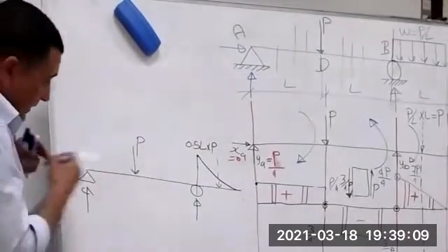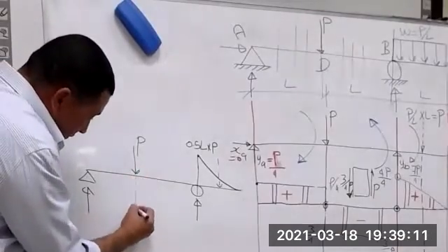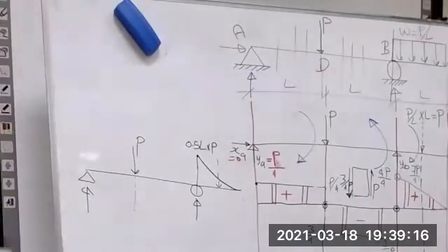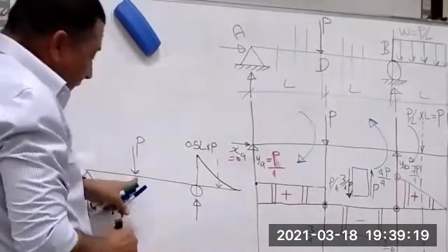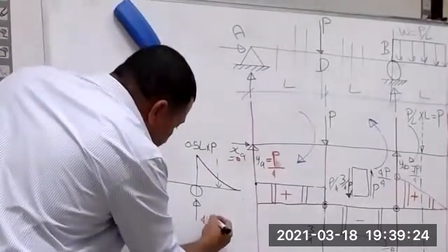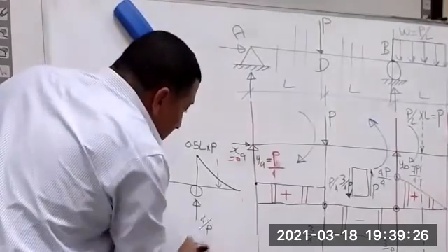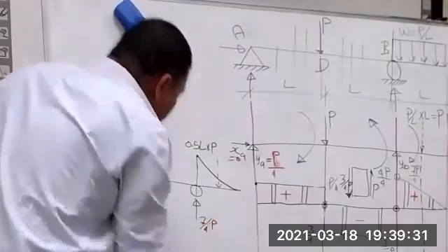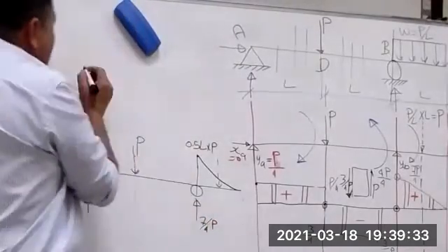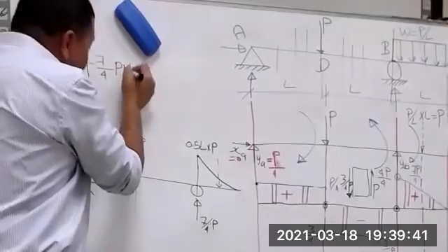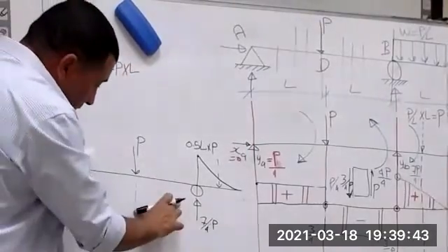And here, the bottom will for sure be like that. Let us see. Put your finger here in this section, down B. The reaction is 7 over 4 B, giving a positive moment here. Why positive? Tension in the lower fiber. 7 over 4 B multiplied by L, correct?